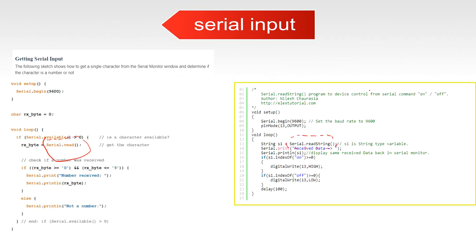So basically, whatever we have typed before we press enter will appear when we use the serial.readString function. Usually the serial port will be waiting for any variable. Only if any data is available in the serial COM buffer will it execute the read function. I will show you later on.